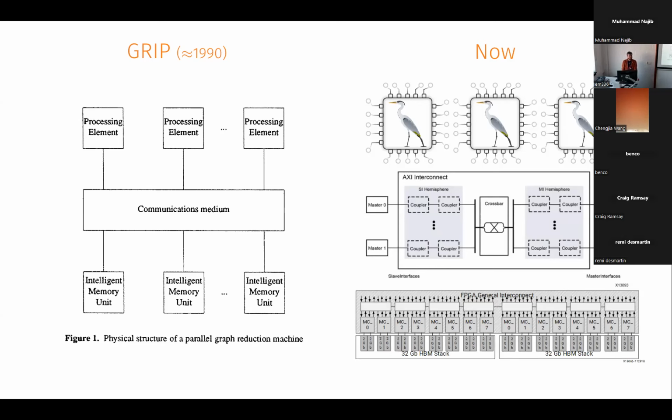And for the FPGA board we have, on the same package, we've got this high bandwidth memory module, which is exactly that distributed shared memory architecture, where for us it's actually 8 gigs, but all of these separate banks of DDR style memory, each controlled by their own controller, and there's some network interfacing in front of that.